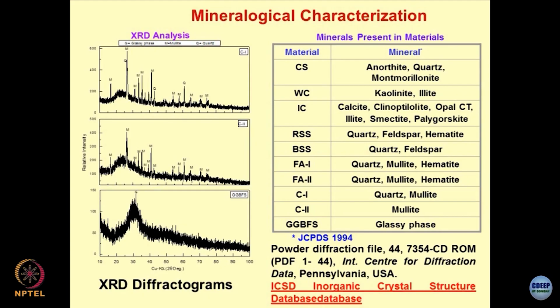On the y axis you have relative intensity and on the x axis you have the 2 theta value of the ray, clear. What I have to do is expose the sample and get this type of diffractogram. I will know the theta value and the peaks of the minerals which are present in the system. Fortunately, all this is done nowadays with the help of software.